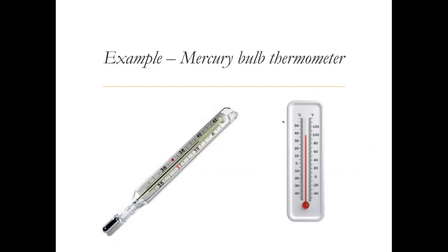This is the typical thermometer that we see. There is mercury here. As we dip it in hot water or any other surface, it expands and then goes up the capillary as per the temperature. It points to that value. So this mercury bulb thermometer is a first order instrument where there is some delay, where there is some energy absorption taking place.